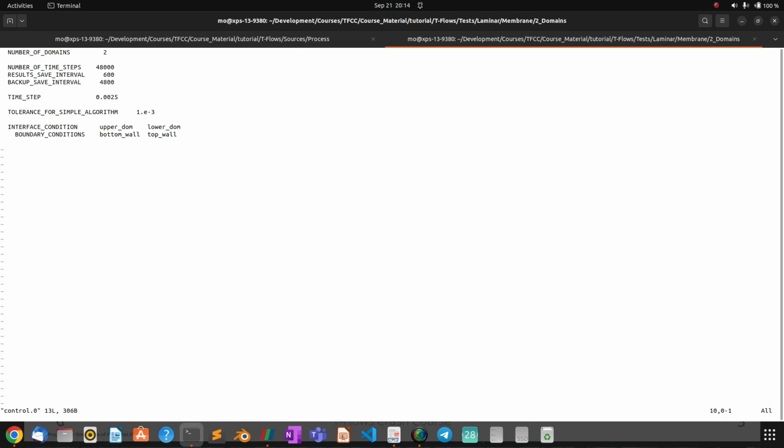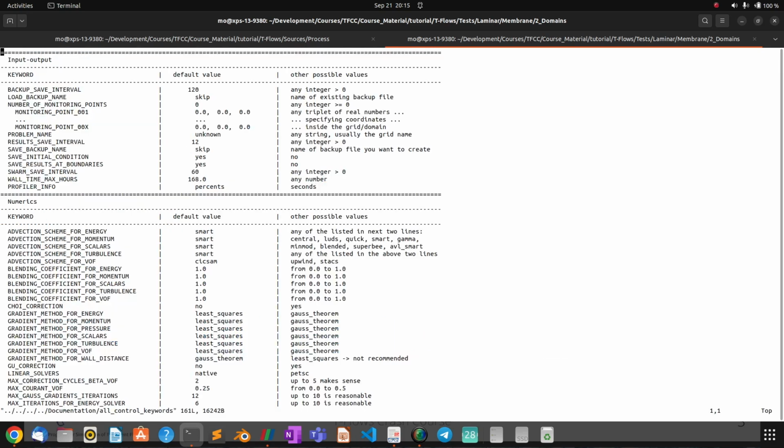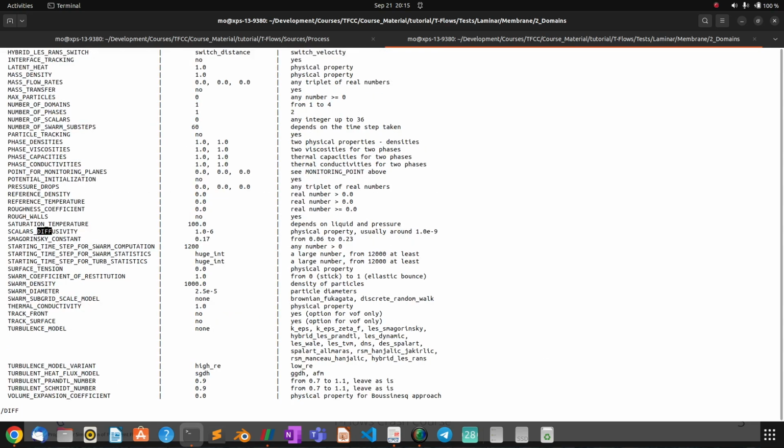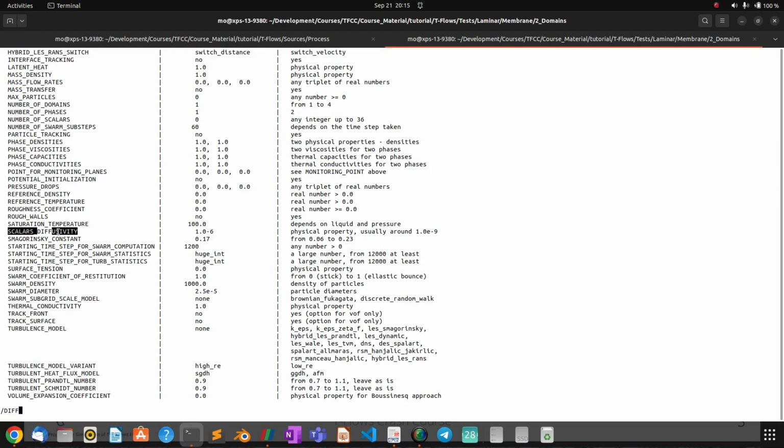It's like a transport variable, like k epsilon, with its own transport equation. But if the flow does not have turbulence, then it doesn't take the diffusivity of turbulence, and it needs a turbulence coefficient to mimic this diffusion effect. This comes into play with this type of keyword. If you go to the documentation, sorry, I guess I misspelled it. In all keywords, if you look for exactly, it's scalar diffusivity, or in the past it was species diffusivity.